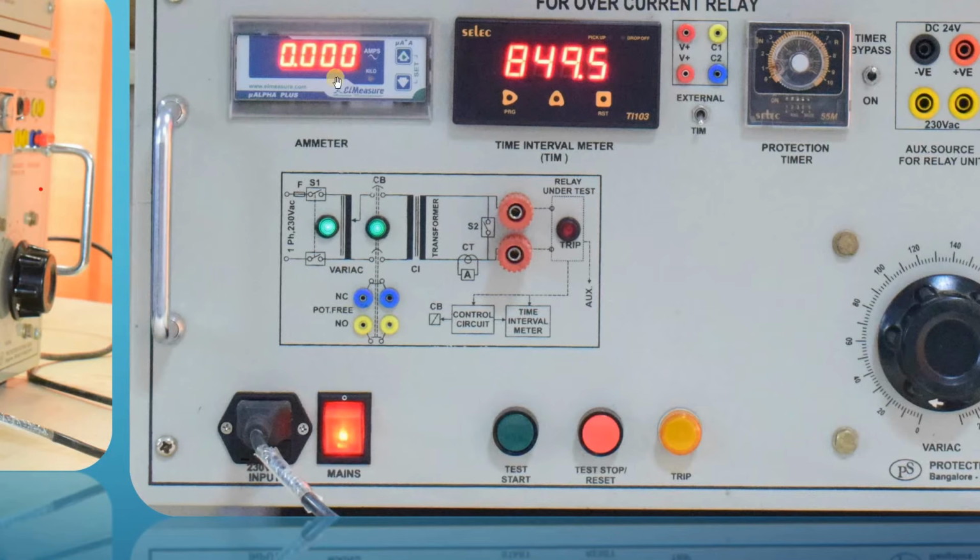And also you can see an ammeter is connected. In which way is the ammeter connected? It is connected through a CT, not directly, because this relay current injection unit can give a maximum of 50 ampere current. If you give a maximum of 50 ampere current and measure with only one ammeter, that 50 ampere has to be measured with it, and 1 ampere also. No such ammeter is there which can give a highly accurate value of 1 ampere as well as 50 ampere at the same time. So that's why the CT is there.